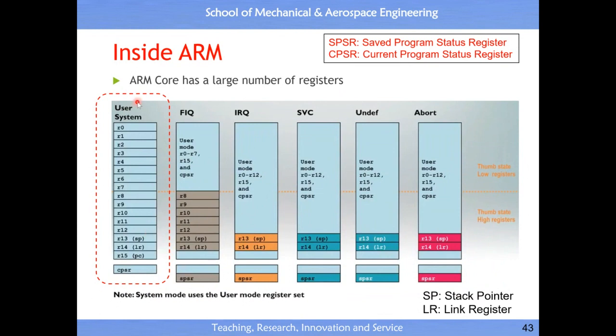We just focus on this, which is the working memory for the microprocessor system. Working memory in terms of registers, from 0 all the way to 15. That means we have 16 registers that serve as working memory. Out of these 16, 3 of them have a dedicated usage. PC means program counter, which holds the address of the instruction. Then LR means link register.